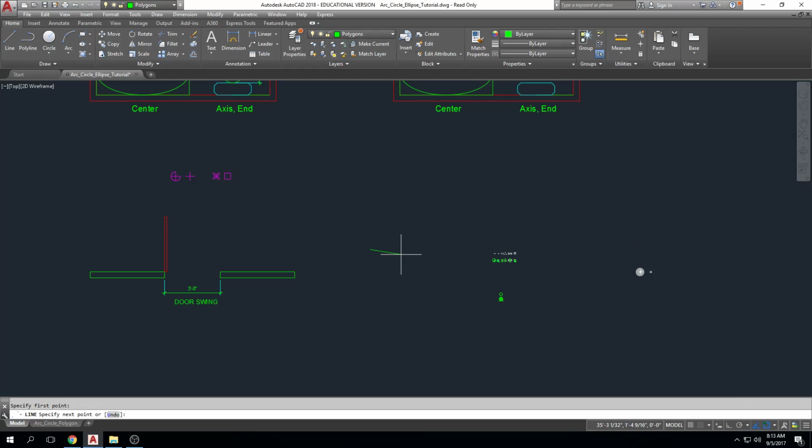We learned last week how to input lines, realistically, and create different types of shapes using coordinate entry, right? So absolute coordinates, polar coordinates, relative coordinates. And realistically, you will likely use the relative input every now and again, but by far and away, you're going to be using just the direct entry method to create most of your geometry, okay? It's just the way it works.